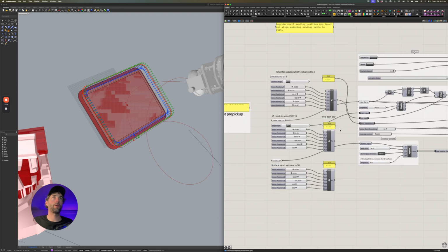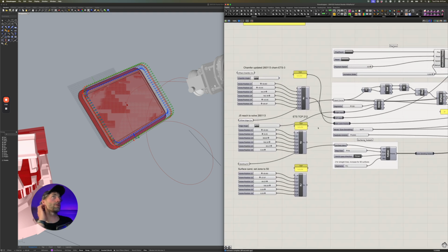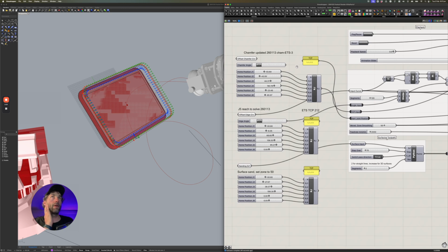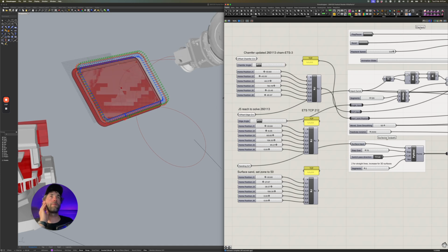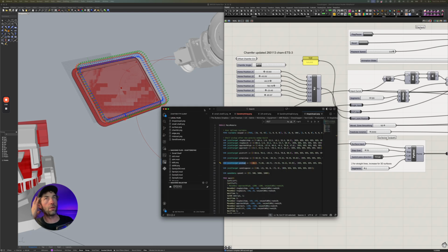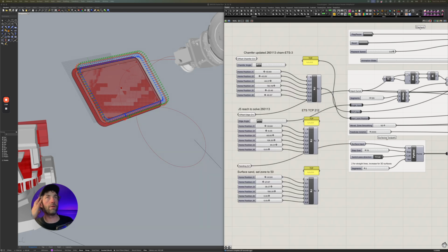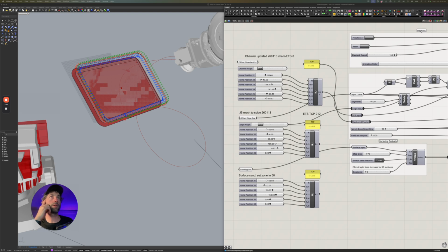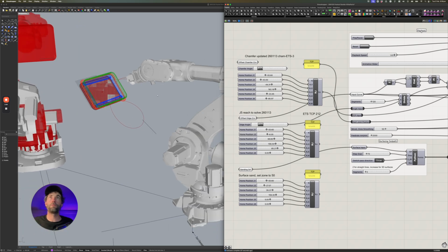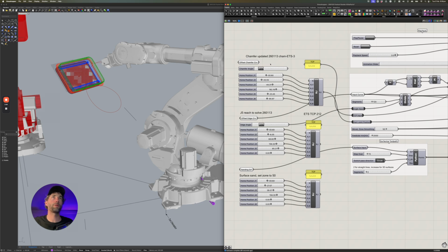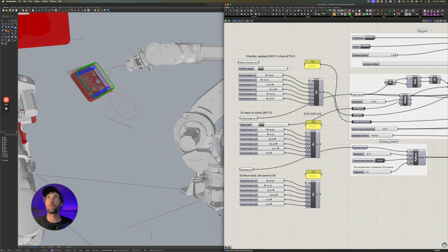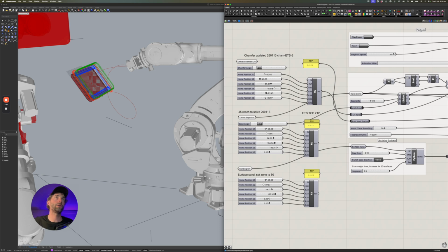So when I'm programming the shelf, I've got this weird setup here where I do it in stages, and then I'm combining the RAPID code into a consolidated program just in VS Code over here. But for the moment, this is how I've set it up. So I can have different start poses for different operations, depending if I need them. At the moment, I'm just recycling the same start pose because it does everything I need it to do.